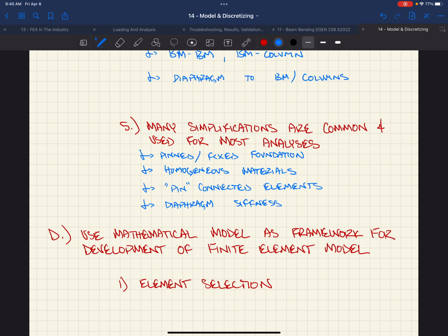It shouldn't matter, right? Like all those shear walls are the same stiffness? Yeah, when you're assuming that they're restraining the diaphragm sufficiently. Because you start looking at that stiffness playing in, then this thing rotates. When it rotates, then there's torsional forces that you're going to have to incorporate. And then you're getting into, okay, now these diaphragms, are they semi-rigid? Are they rigid, right? This is that scale.